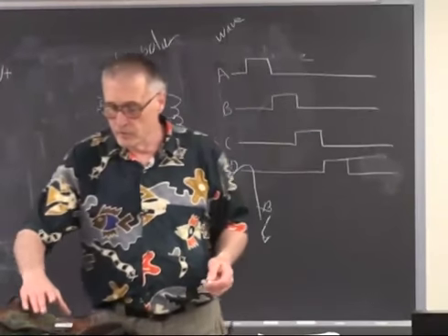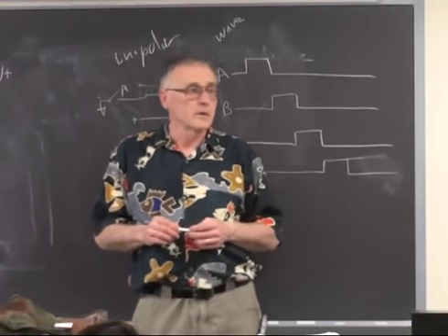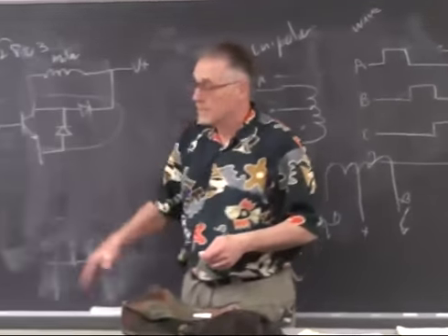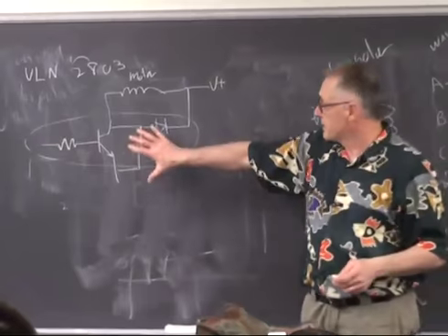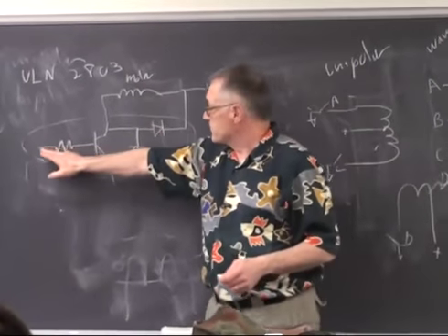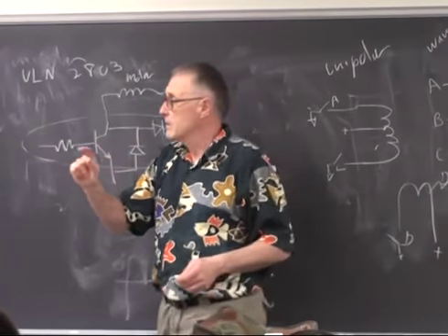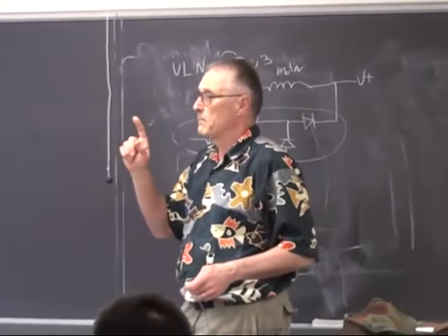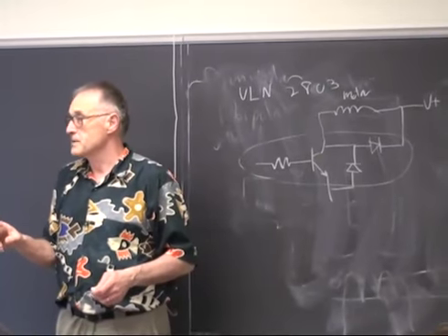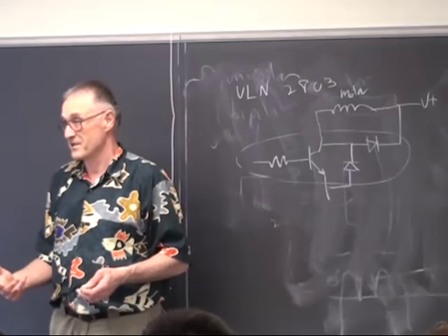Probably what most of you will do is to roll your own, in fact, using a low-level driver like a ULN 2803 to get the power necessary to run the motor, and then drive these directly off of port pins. If you're using unipolar motors, you can get away with this because there is no set of switches that will destroy a transistor.